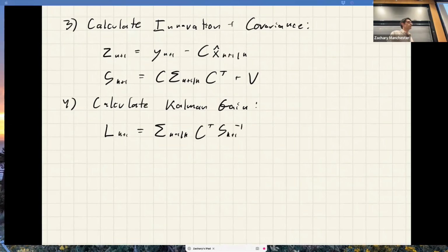Is it going to be a problem if any of your sensor sub-collections does not hold an observable system? That's totally fine, as long as the total system is observable. That's the whole point: I can make partial measurements whenever I want, and the filter is fusing all of that. A given measurement at a given time could be some tiny scalar measurement that's definitely not enough to reconstruct the whole state, but this is sensor fusion.